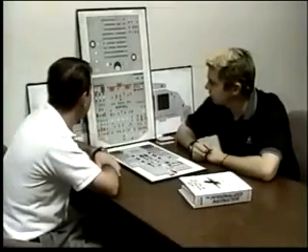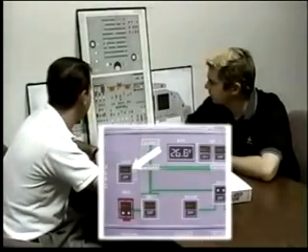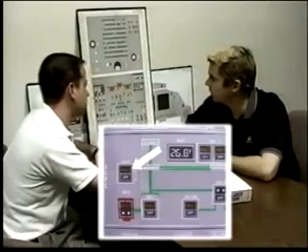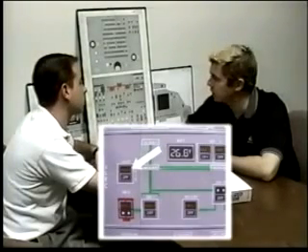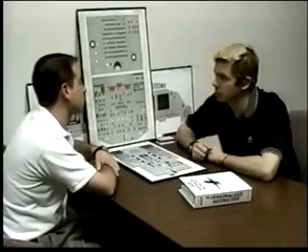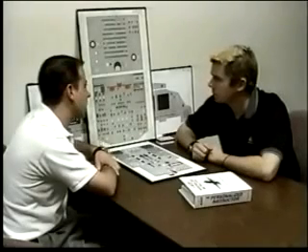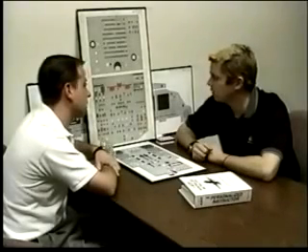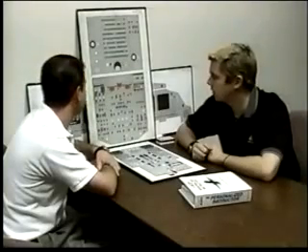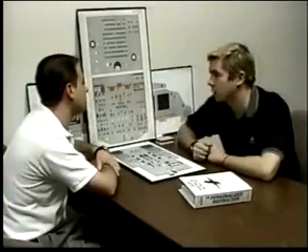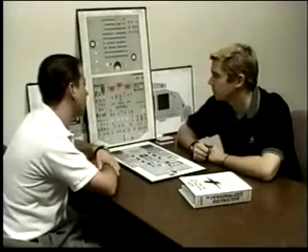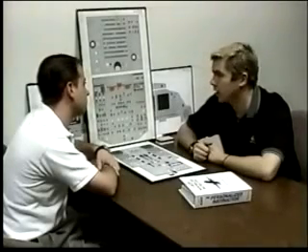Let's talk about the galley switch. Fault in the galley. What does that indicate? Indicates that any generator that is an engine-driven generator or the APU generator has a load in excess of 100%. Doesn't it shed the galleys completely? No. Or by shed automatically? No, the galleys are not shed until you select the switch to off. And then what occurs? The galleys are unpowered.